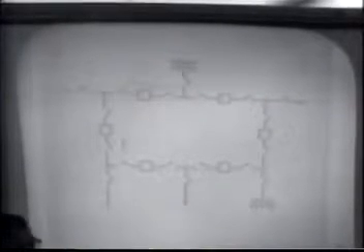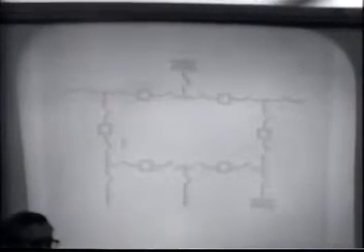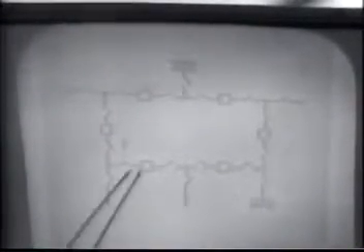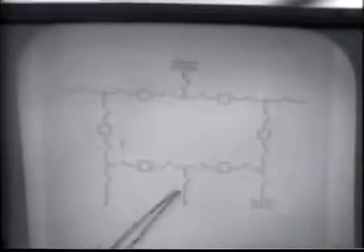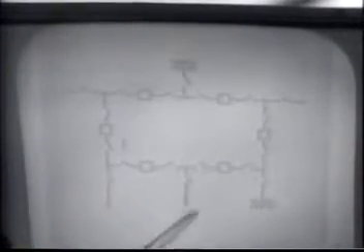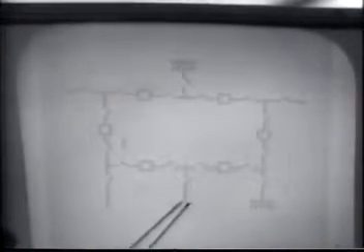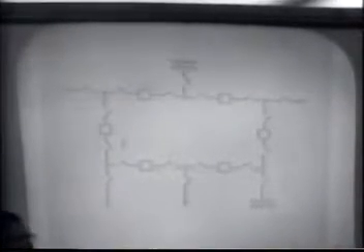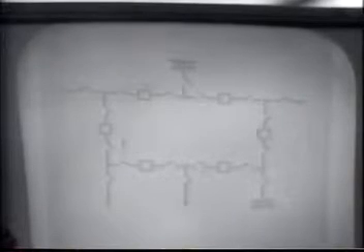The ring bus still has a single circuit breaker per circuit. As you can count, the number of breakers is equal to the number of transformers and lines. However, no particular breaker is assigned solely to one circuit or transformer.